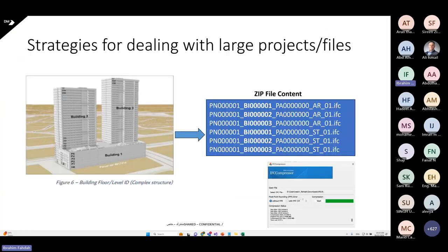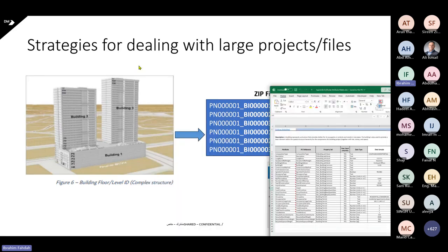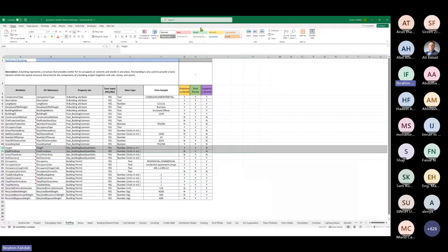The other thing to quickly highlight is also useful. In the standard, I have a few questions on Teams asking what information is required to submit with the BIM model. Aaron highlighted that when you fill in the information in your Revit model or the BIM model, or if you're using other authoring tools, you need to always refer to this file, the attribute matrix.